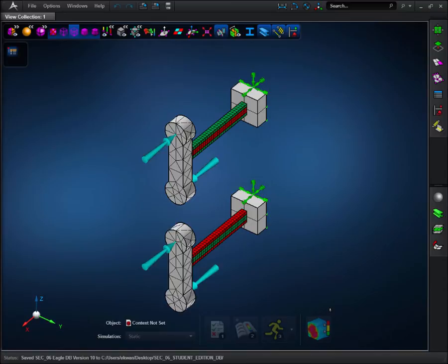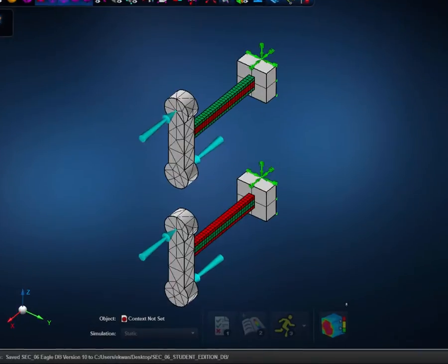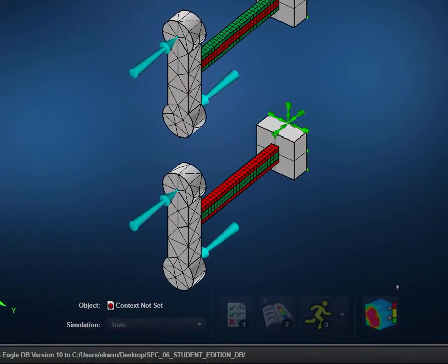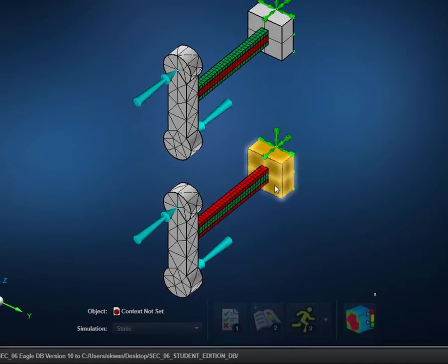beams. As in the previous beam demonstrations, each subassembly consists of the beam, a part used as a tool to apply the load, and a block on which the constraints are applied. This demonstration model is different in that each beam is made up of 3 distinct solid parts which are assigned the different materials. These 3 parts are glued together, and each beam is glued to the tool and block.